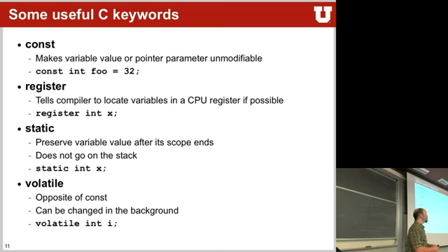So if you declare something as const, it will go into the data section of your linker script. And the data section is usually in ROM, which is a memory location. Eventually it would get read from that memory location into a register to do operations on. But it's in ROM and not in RAM, because you can only read from it. You will never be able to write back into it unless you do a more complicated operation on the flash memory.